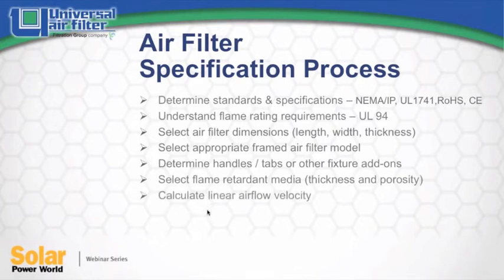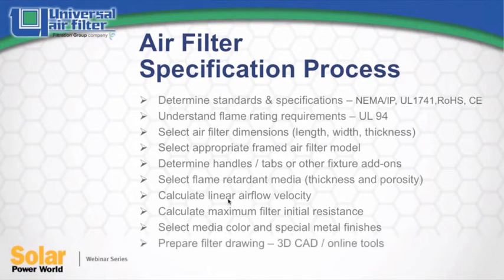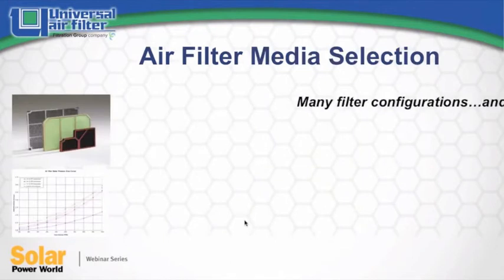Determine your linear airflow velocity requirements and calculate the maximum pressure drop that a filter may introduce into your system. Select media color for industrial design purposes, and add special metal finishes, and prepare your custom air filter drawing. You'll also want to pursue custom samples to test and evaluate in your equipment.